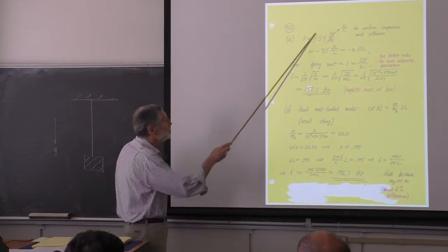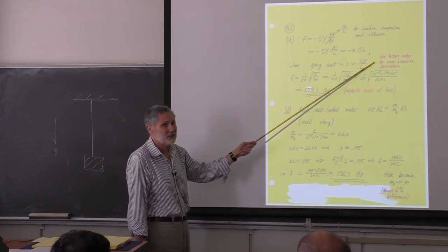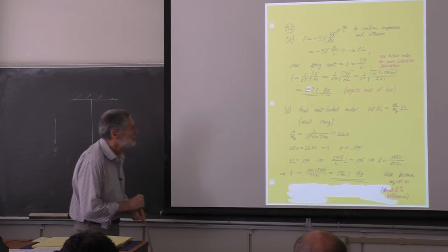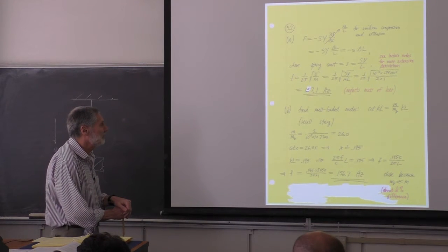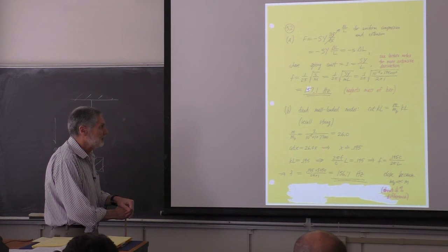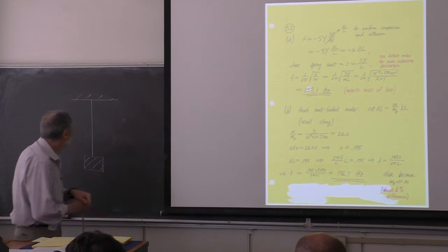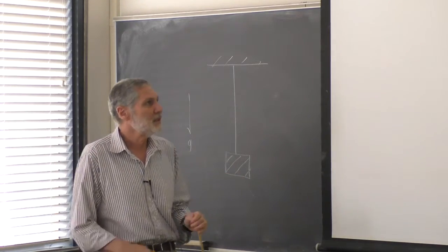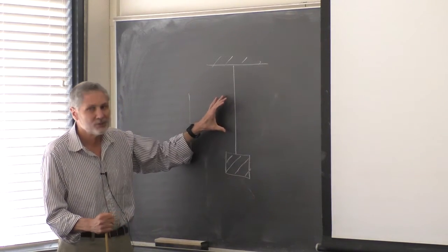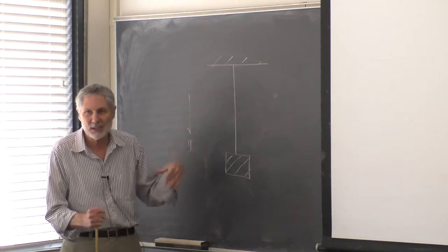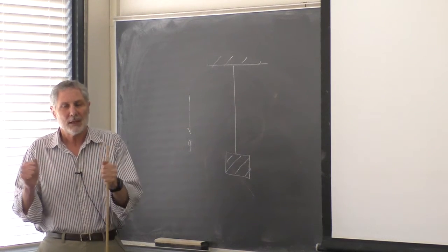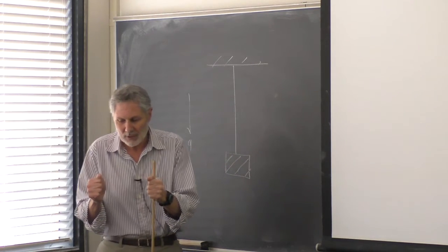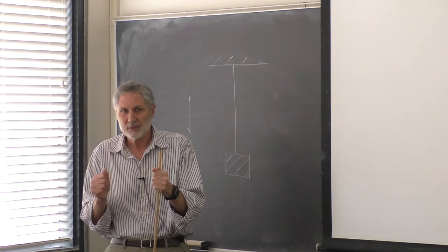Now, this is a quick way of deriving something we talked a lot more about in lectures. So you can look back and remember we had that special topic in the lecture notes, because this comes up a fair amount. Dealing with the spring, thinking of a bar as a spring, so it has a spring constant. And it comes up in cases where you have approximate uniform compression and expansion, because that's how an ideal spring behaves, right? An ideal spring, and by an ideal spring I don't just mean it obeys Hooke's law, but I mean that we don't worry about waves on there.